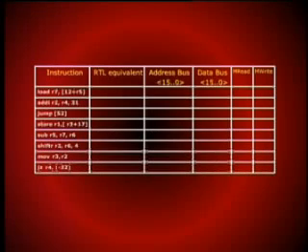The next column indicates the activity on the data bus. We need to indicate what would be available on the data bus. The last two columns indicate the memory read and memory write. When read is active, it would be 1, and when it is inactive, it would be 0. Similarly, write could be either a 1 or a 0. Naturally, both of these could not be simultaneously 1, because at one time either memory would be read or some data would be written into.